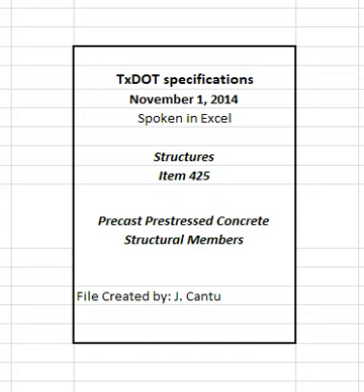Support concrete box beams and U-beams under the solid end block area during handling, storage, hauling, and erection. Separate members with blocking arranged in vertical planes that will not crush under load when members are stacked. Stack members so lifting devices are accessible and undamaged. Use dunnage or blocking material that will not damage or stain the required finish. Rearrange improperly stored members and inspect them for damage. Members that are improperly stored and become cracked, warped, or otherwise damaged in storage may be rejected. Securely tie or brace all beams during erection in accordance with minimum erection and bracing standards.